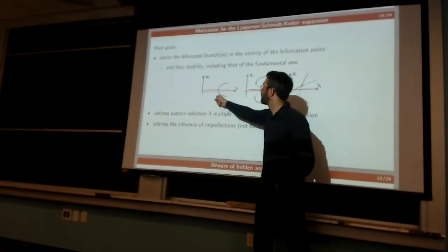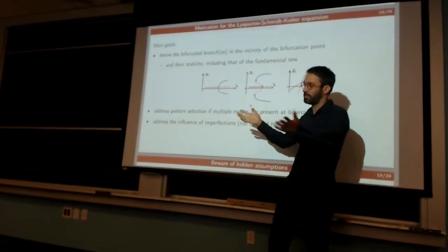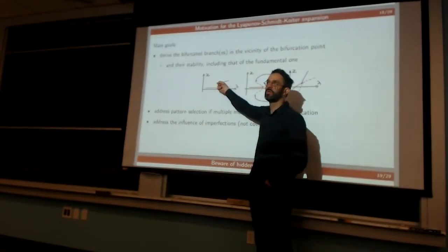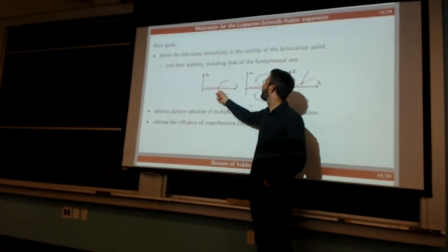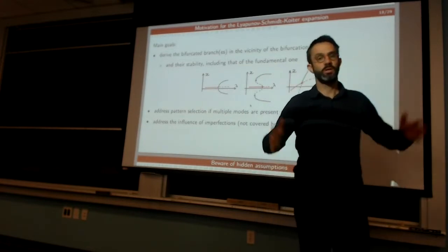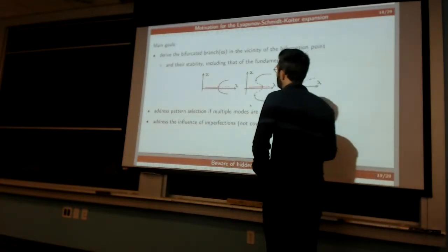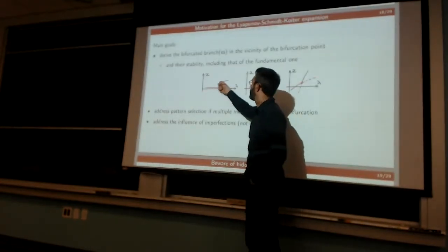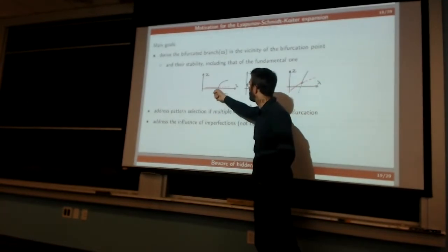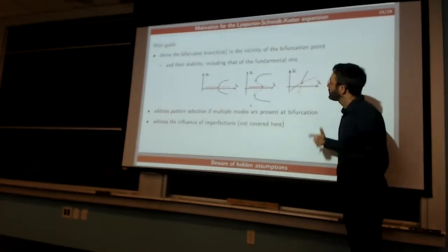So that's the case of the symmetric bifurcation, where there's a symmetry argument, just because your system happens to be symmetric, that tells you that whenever you have a bifurcated solution, you have also another bifurcated solution that has exactly the same energy. So typically, if you think of the elastica, you have one buckling on one side or the buckling on the other side, and they should be equivalent. So you need to have this parabolic shape. But you can't tell, unless you do detailed analysis, whether the parabola is on the curvature to the right or to the left.